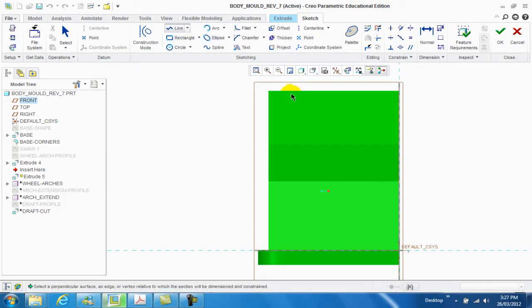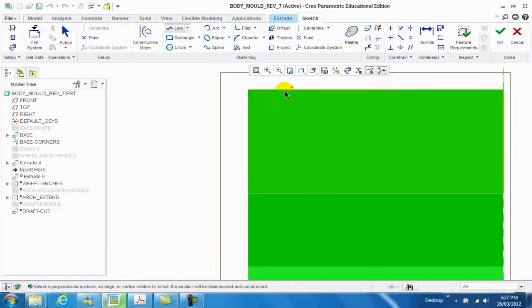Now, holding down the Alt key, something a little bit new in Creo, is you hold down the Alt key. You used to click View, Sketch References. Now you click on this, and you're going to actually click on this button here until you see it just drew it. Escape. It's got my sketch reference going across there.